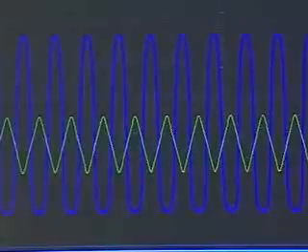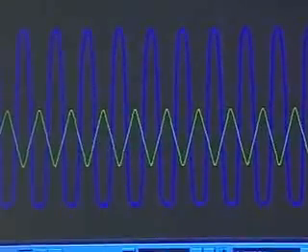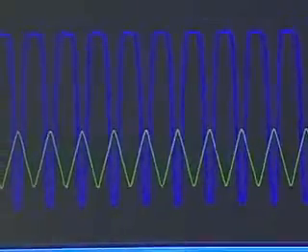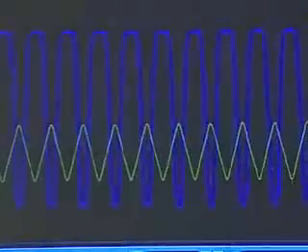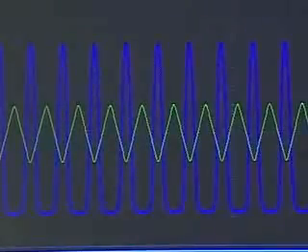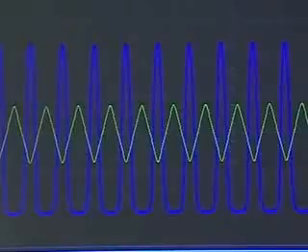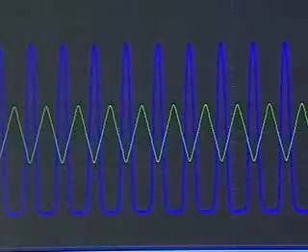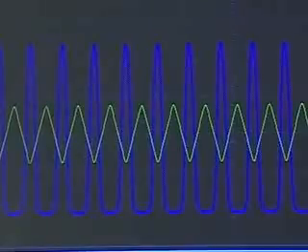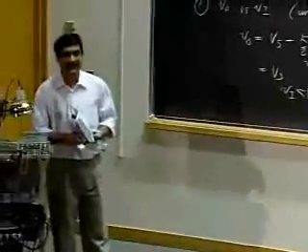So I showed you three things. One is very little offset, that was like so as the thing comes down. Very high offset, gets killed again, and the right amount of offset. But notice that we still have a problem, even with the right offset: the output is not linearly related to the input. It's nonlinear. And the answer to get a linear response is good old small signal stuff. We'll look at the small signal part in the next lecture.